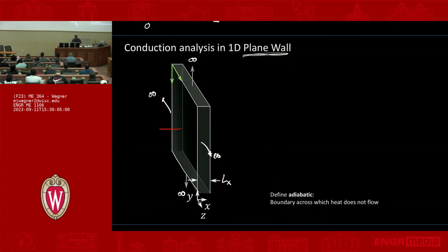All right, so let's take this idea and go a little bit further with it. So let's say in this example we have some heat flux, and I'm applying a heat flux uniformly to this surface on the left. Right, that heat flux is of magnitude q dot double prime, right? So it has some units, watts per meter squared. And the question is, in this situation, I've got a uniform heat flux. The plane is essentially infinite, but it has some thickness. Will there be any temperature gradients? Will there be any reason for heat to flow in any direction other than x?